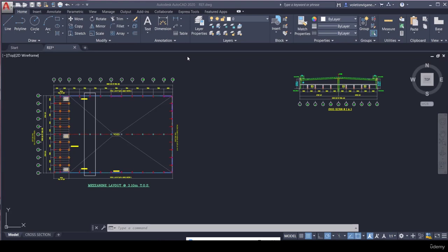Okay. Hope you got it. What I'm saying is, the one thing you have to know is all the dimensions. All the nodes we have to create a structure in STAAD is along the center line only. Along the center line of the rafter, along the center line of the column only, it will take, and then it will be giving offsets to either side.